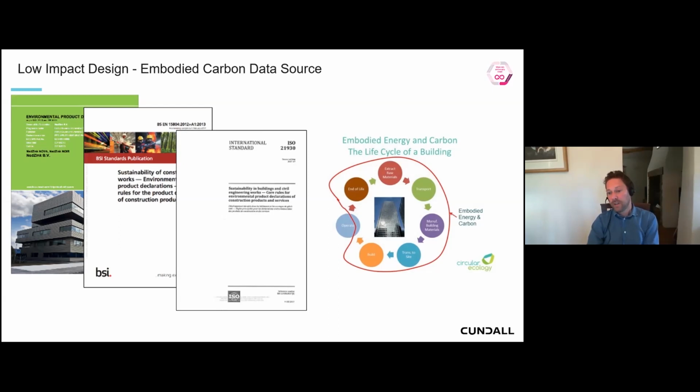Circular Ecology also have produced the ICE database with the University of Bath, which is good at the design stage, because rather than focusing on one manufacturer, it looks at a typology of material and then does a standard distribution assessment. So it gives market standards, if you like, in terms of what is a likely carbon footprint for those materials at the design stage before you know who your manufacturer is.